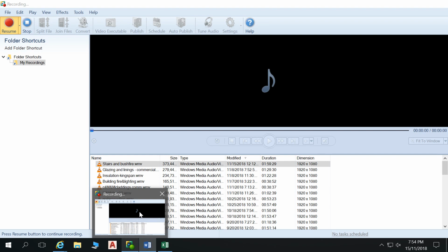But if we're going to have 3 or 4 metres clear in front of that building, and then the car parking happening there, then we don't actually have a fire source feature, and an FRL is not going to be an important consideration for any external treatments on that building.